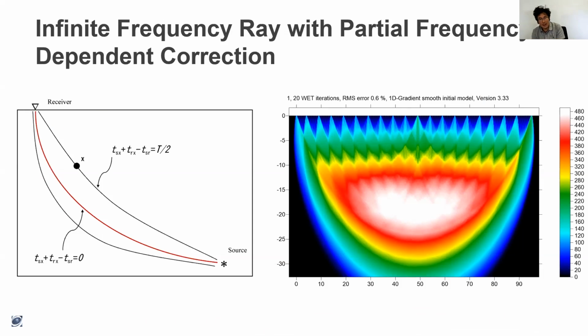That being said, because the Fresnel volume in the software is user defined, you choose a center frequency for your refracted arrival. If you choose it to be too wide, what will end up happening is you'll smooth your model out artificially, as opposed to if you choose it too narrow, you can start to introduce artifacts.